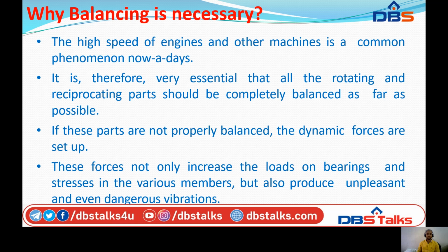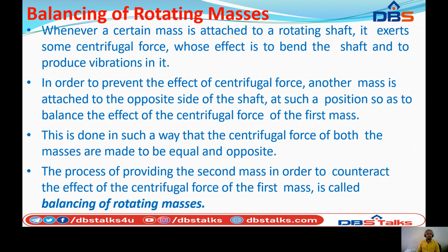Why is balancing necessary? As we discussed, due to the high speed of the engines, all the rotating and reciprocating parts should be completely balanced in order to avoid dangerous vibrations, and dynamic forces that are set up. Now, the balancing of rotating masses.